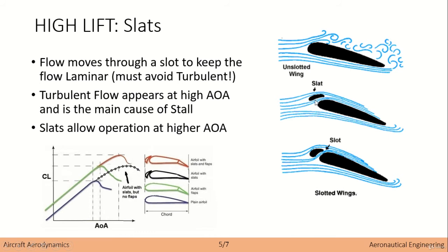In this way, we are able to transfer some of the wind which is over here, which otherwise would go down, or would behave unstably over this part of the wing. What we do is direct this air into the slot, which is the slot between the slat, the physical material, and the wing. It may seem a bit stupid, but the idea is quite clear and it works very effectively.